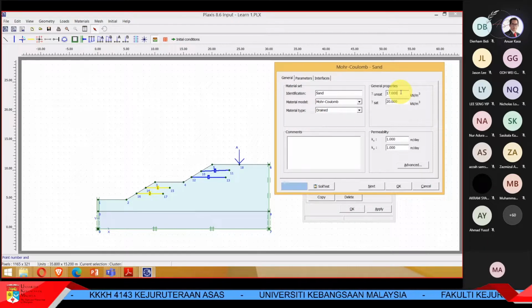If we look here, the K is permeability. For sand, normally we put 1 meter per day. This is the Young modulus. You can get this value, the typical one, or you can do the consolidation lab test. For consolidation, you can get this value. And also nu is Poisson ratio. If you learn strength of material, you know. For soil, it's about 0.3, 0.25, 0.35 around that.